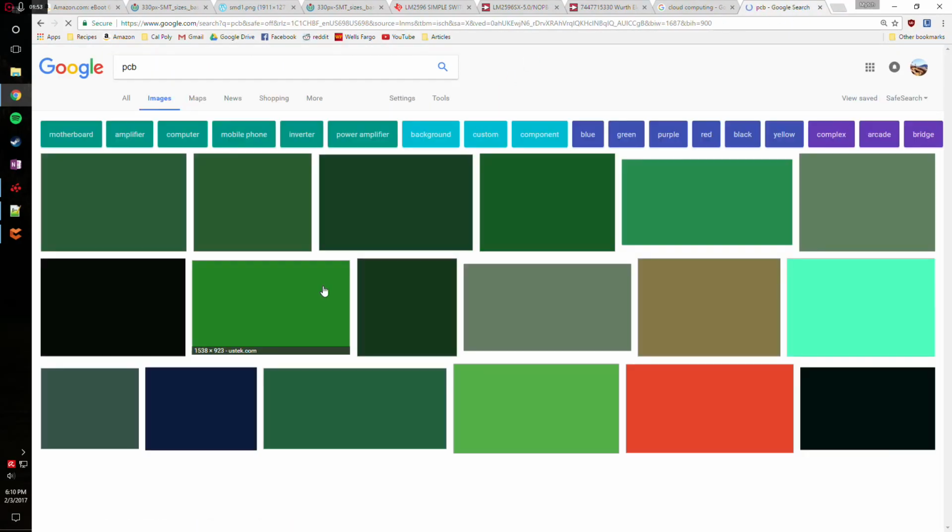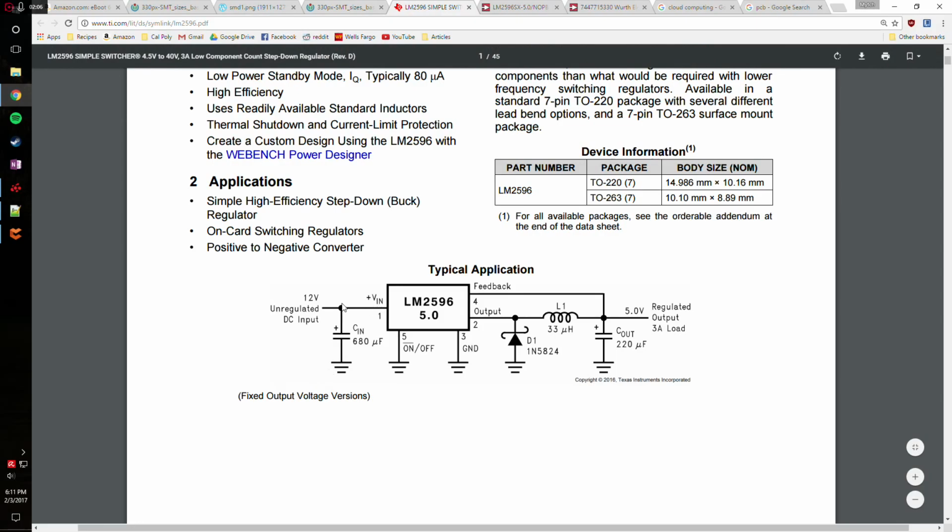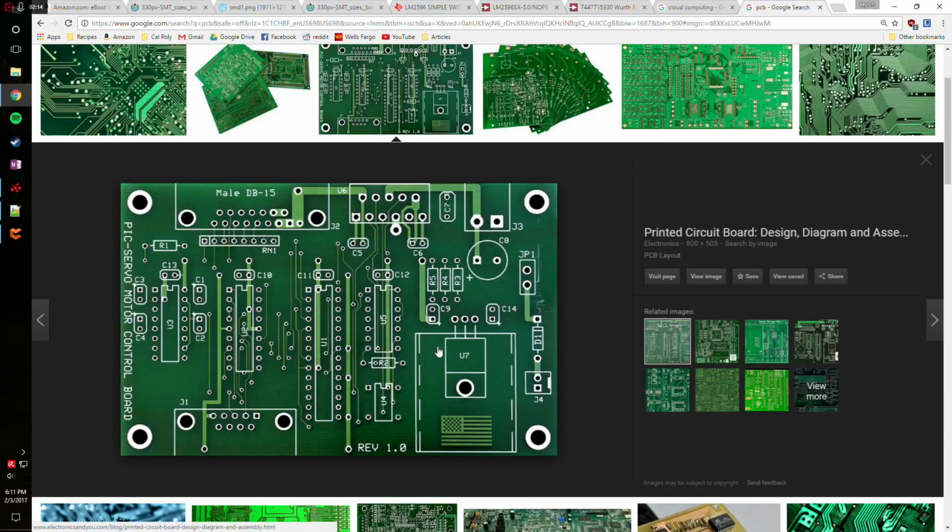So using a schematic, you're able to tell the Circuitmaker software, whichever software you're using, connect pin 1 to this capacitor and connect that to ground. And then when you turn Circuitmaker into your PCB editor, it knows what's connected to what, helps you route it. So here's an example of a PCB. The person who designed this had to tell the computer that connect this pin of the IC to whatever this ends up being connected to and stuff like that.